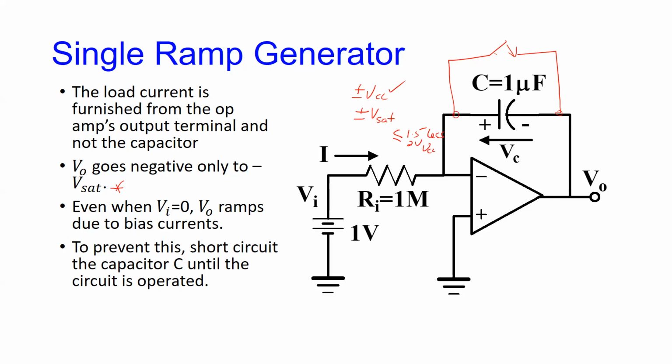But if you're taking a regular op amp like a 741 or a commercial LM308, those kind of things that you met already, generally if VCC is plus or minus 15 volts, the saturated voltage may well be plus or minus 12. That's about as good as you can get, right? Don't try to aim for anything more. So you have to bear that in mind. This is part of the selection process when you're dealing with electronic components.